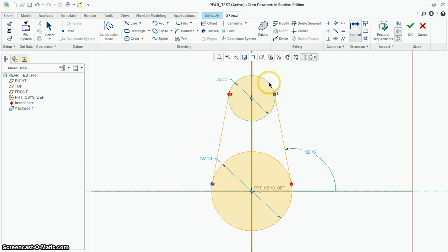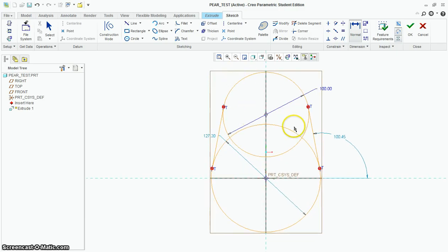We're going to double click the circle and middle click outside of it to add a diameter dimension. If I wanted a radius dimension, I would single click the circle and then middle click outside of it. So 1 click for radius, 2 clicks for diameter, and then we'll change this to 100. Enter. Now it looks a little strange, but that's okay. So we'll keep drawing here.